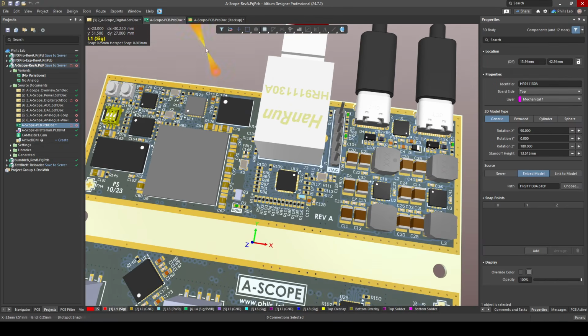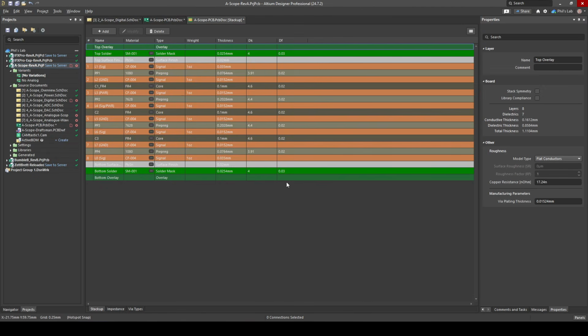So let's firstly explore the stack-up. This is an impedance control PCB, and I did talk to my manufacturer, in this case PCBWay, to get suggestions and recommendations on the specific stack-up for my requirements and for my impedance control requirements, and then also calculations for what trace widths I need to meet certain impedance specification. Before we move over to impedance control, the stack-up is an 8-layer board.